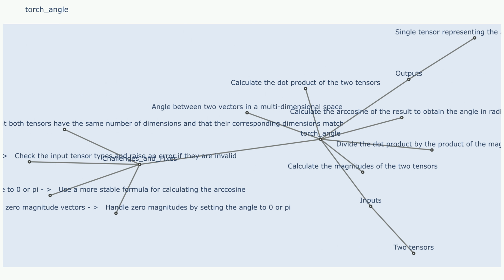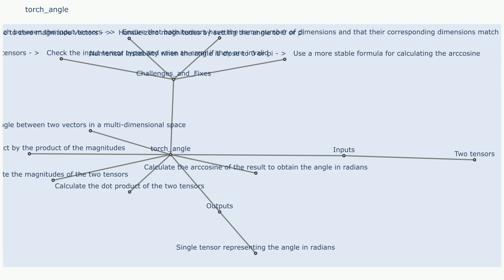Reduce welding current, decrease the welding current to reduce the heat input. Use a smaller diameter welding electrode. A smaller diameter electrode will reduce the heat input and penetration.